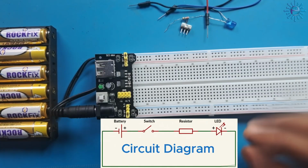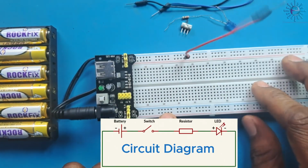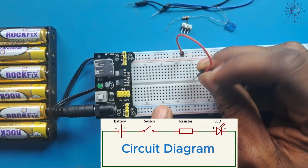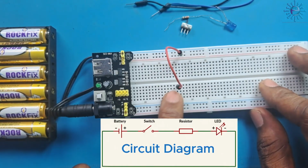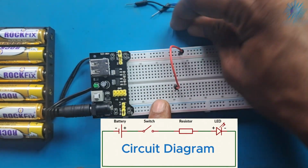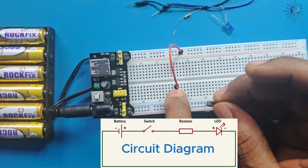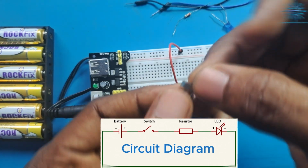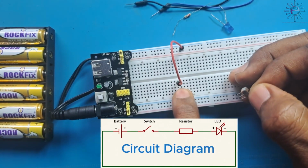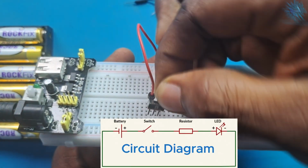The first thing I will do is to connect a jumper wire to the 5 volts rail of our breadboard and connect that jumper wire to any hole in the middle of the breadboard, as you can see here. Then the next thing I will do is to connect a switch to where I connected the second leg of that jumper wire, which is here. So I will connect one leg of the switch to this hole where I connected the other end of the jumper wire. So I will connect it like this.